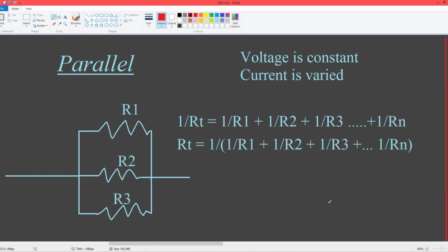Now, parallel circuits. These can be a little bit harder to fully understand. A parallel circuit is a point when the current divides and then reconnects later. The electrical potential across each element in parallel is equal. It is the current that changes, which is the opposite, of course, from series. The current splits across each element, and when you know the resistance and the voltage, you can use Ohm's law, once again, to find the current in each element.